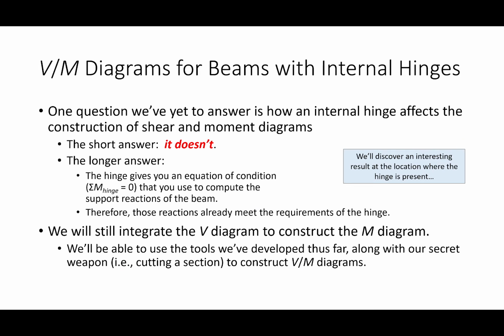Okay, so how does an internal hinge affect the construction of a shear and moment diagram? The short answer, it doesn't, okay? The process of constructing the shear and moment diagram is not affected by the presence of a hinge, okay?